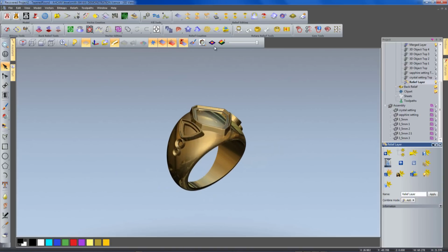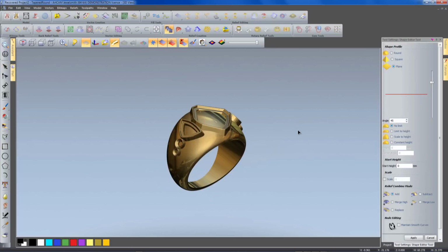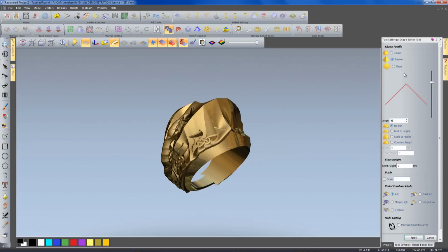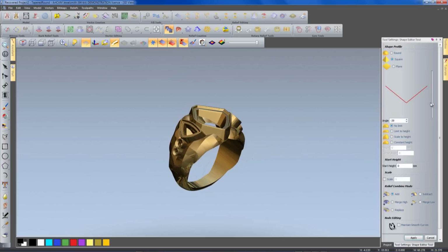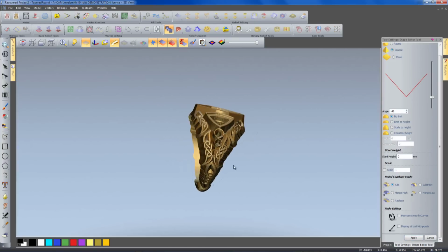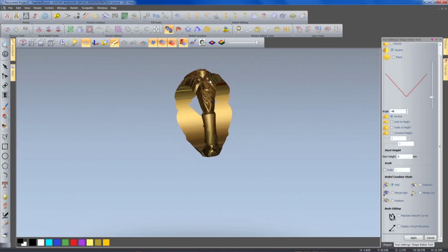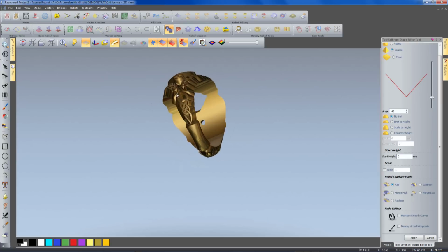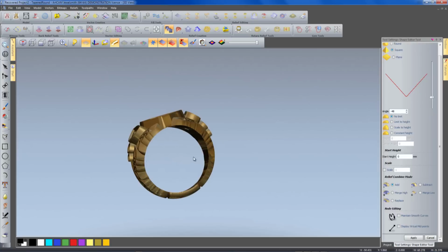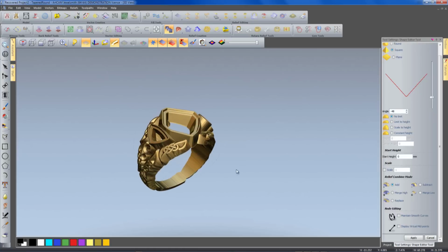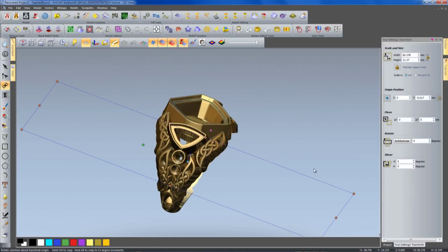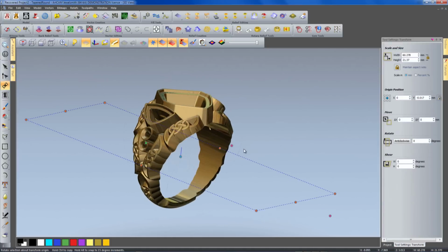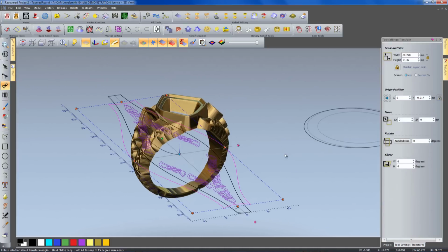All the vectors are still selected underneath, and inside, as long as you're in the relief model, just press F12 or the shape editor icon, and now we're going to go to minus on the square setting. So we're going to pick square and just use a minus value in here, and you can see what it's done now. It's removed all the sections of the model that you don't want to keep and just kept that nice curvature of the Celtic weave itself.